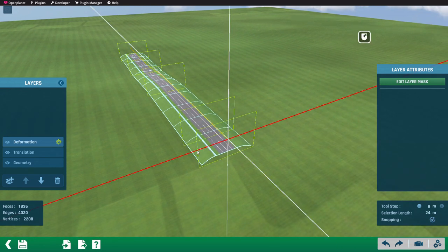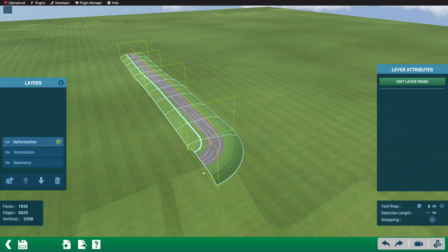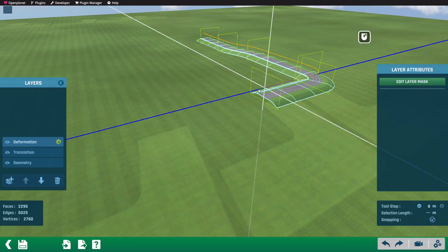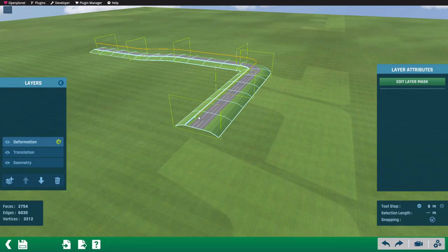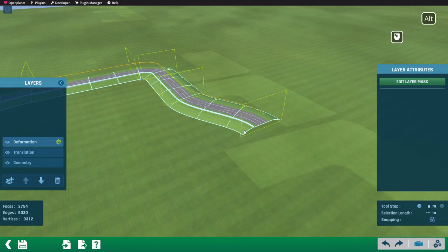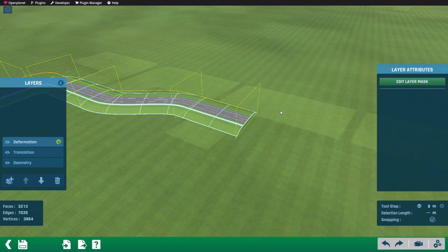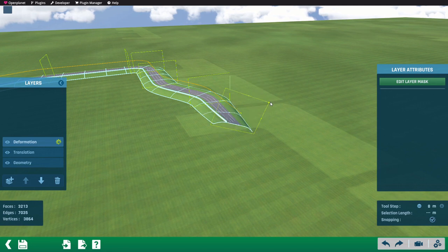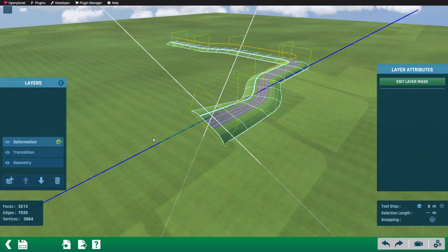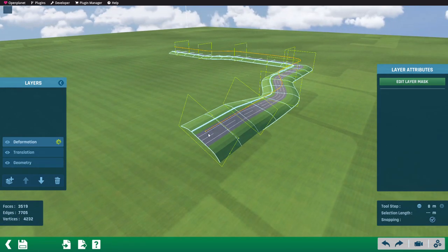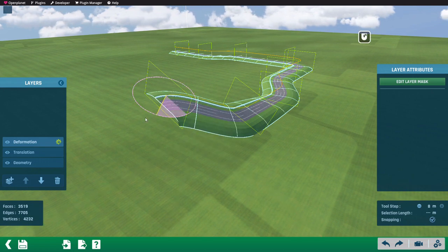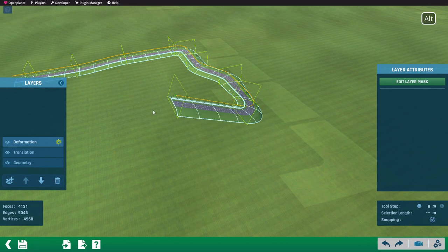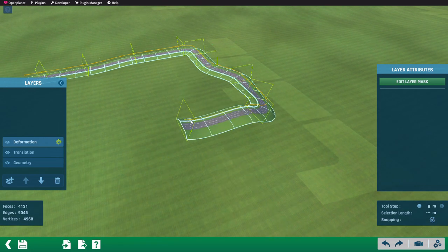Advantages are: one advantage is the flexibility to use various combinations of slopes, bankings, and direction changes without needing to worry about understanding the precise mathematical orientation of the spline. This is particularly useful because bankings can transform into slopes during turns, making the mathematical orientation complex. However, with this method, since the deformed item doesn't need to be connected to another one afterwards, such complexities are not a concern. Another advantage is the ability to easily apply additional modifying layers to the item, such as scale layers or rotation layers.